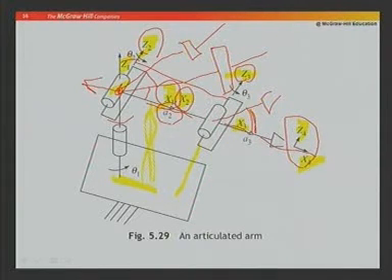So, there is a theta 3 here, and then the distance between Z3 and Z4, which is this distance, is A3, and the angle between Z3 and Z4, since they are parallel, is 0. So, this way we complete the DH parameters of this articulated arm. If you have quick questions, I can wait for about 15 seconds before I show you the transformation matrices and the forward kinematics result.